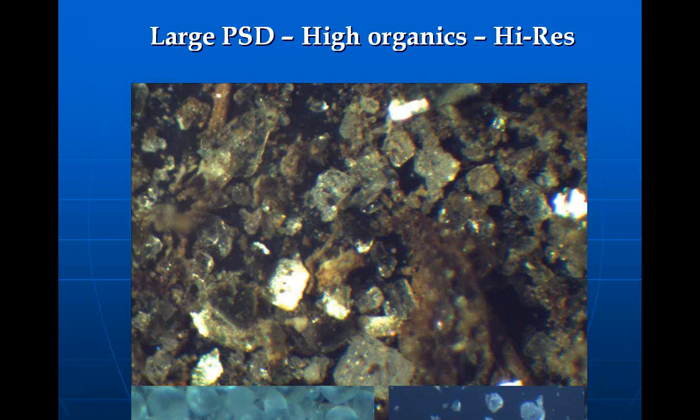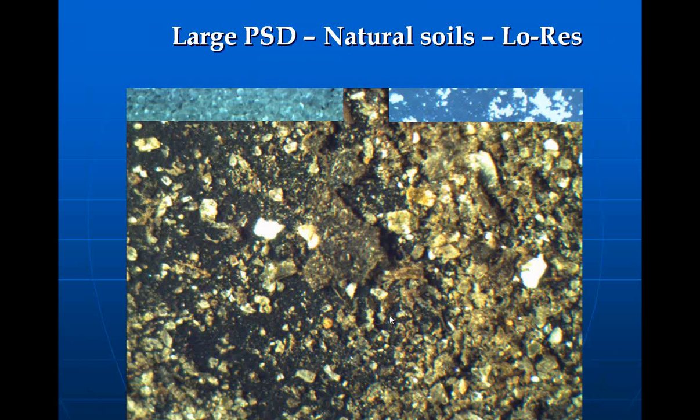It could be coming off of the material that's used to build brake pads. There's a lot of other possibilities there without some detailed spectral analysis and some other things. This is difficult to tell. But these are much larger particles, and we've probably got an average 200 micron particle size definition here. That type of material is the type of material that a separator would be very good at.